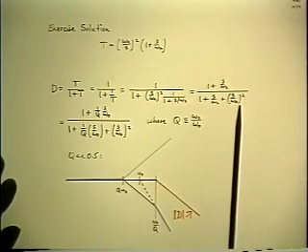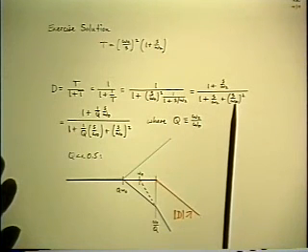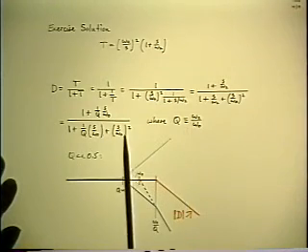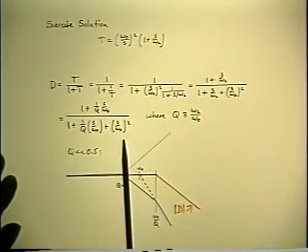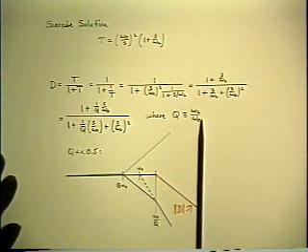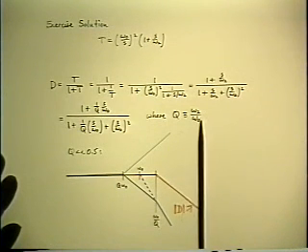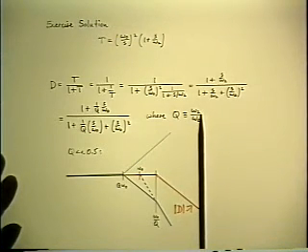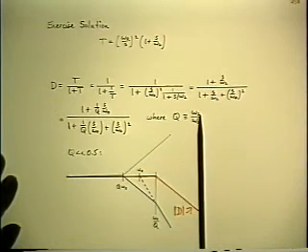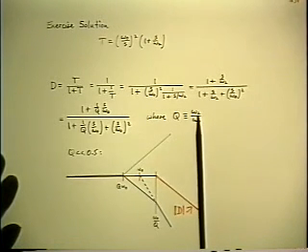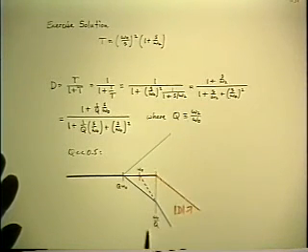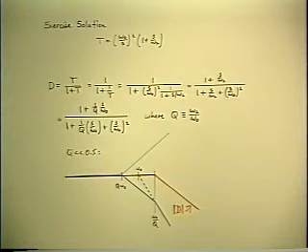And so you define a corner frequency, although as a matter of fact it's already defined, it's omega 0, and you define a Q factor in order to put the quadratic into the usual normalized form. And the Q factor is omega 2 over omega 0. Omega 0 is the fixed reference. Omega 2 is the position of your adjustable 0. And it can have any value, again, from 0 to infinity, depending on the position of the compensating 0. So you sketch the typical case for each of the ranges.